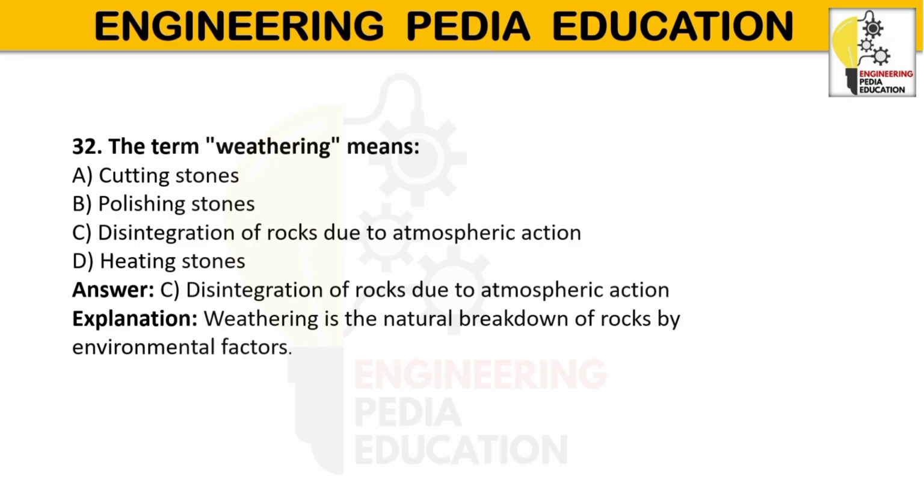Weathering is the disintegration and decomposition of rock and stone due to the action of atmosphere, water, temperature changes and biological agents. Physical, mechanical weathering is due to temperature change, frost action, wind, etc. Chemical weathering is due to oxidation, carbonation, hydration and solution. Biological weathering is caused by roots of plants, bacteria and other organisms. Effects: reduced strength and durability, cracks and disintegration, increased water absorption.